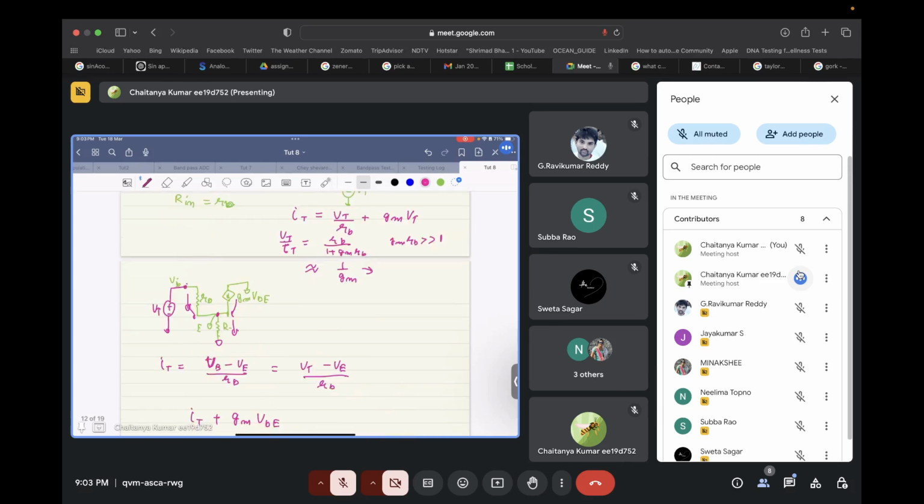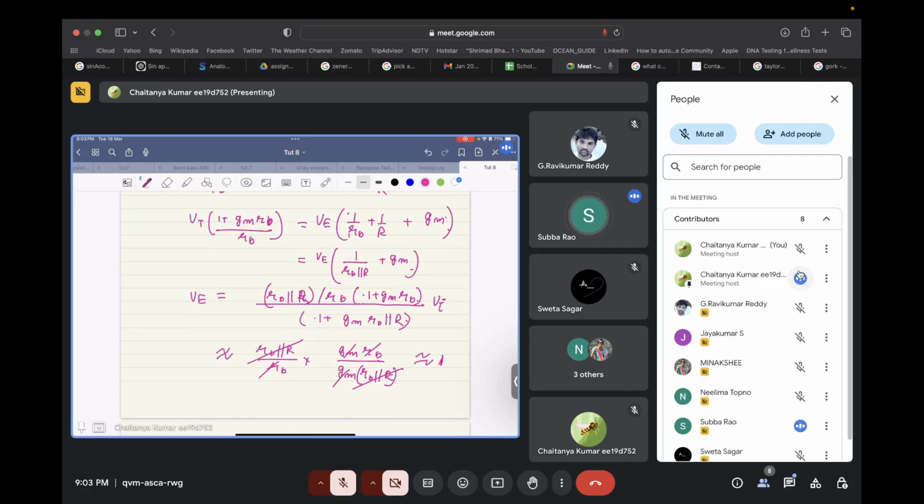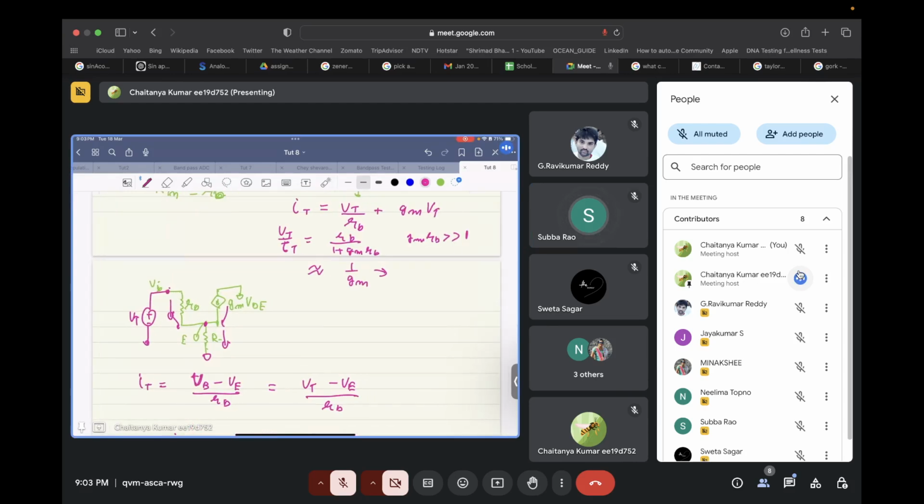Okay. So our emitter voltage is equal to the input voltage. The gain is equal to unity. And you might have heard, right, the common collector amplifier is also known as a unity follower. You have heard this term? Voltage follower. Yeah, voltage follower or unity follower. Okay, so basically what happens is, however my VI is swinging, in the same fashion my VE is also swinging.